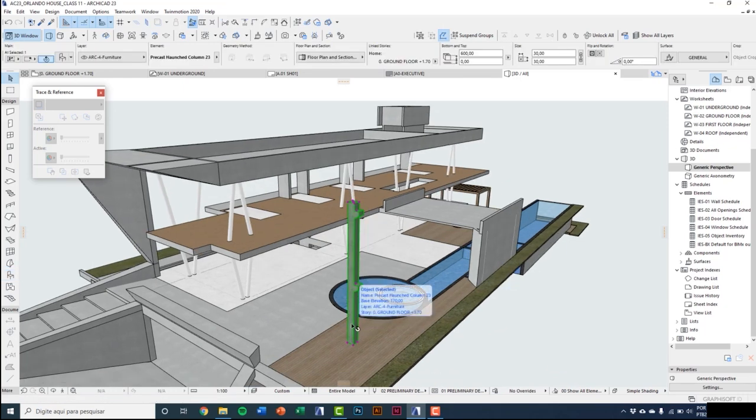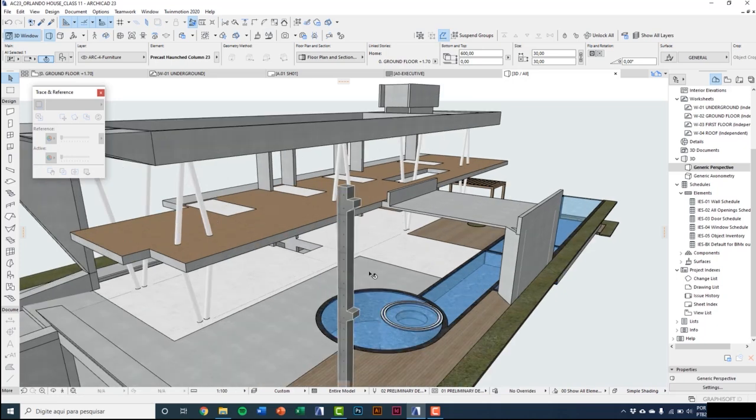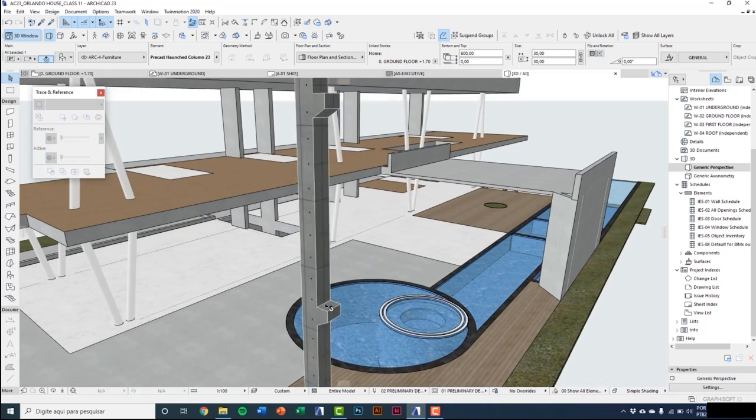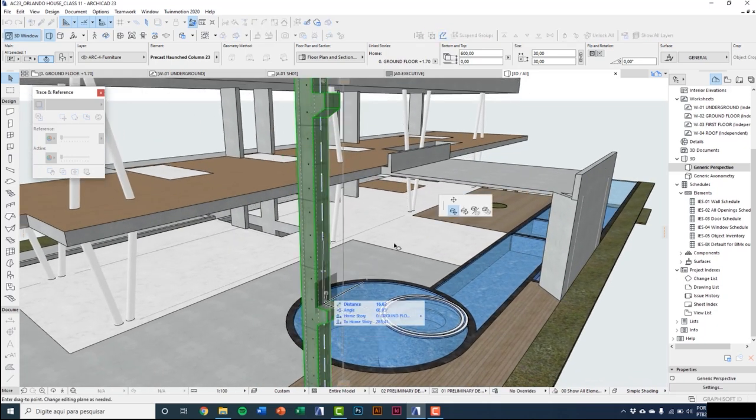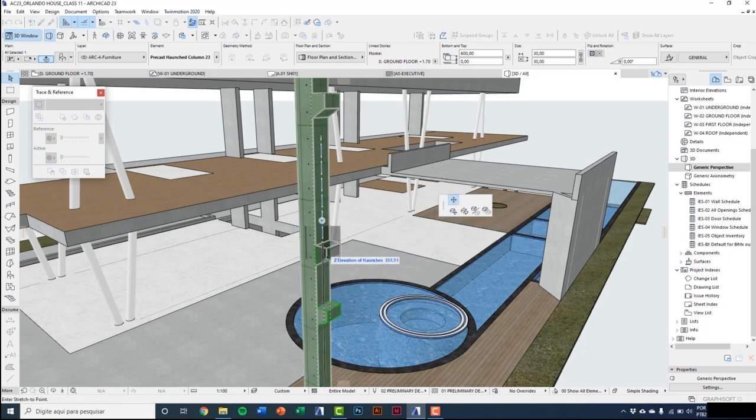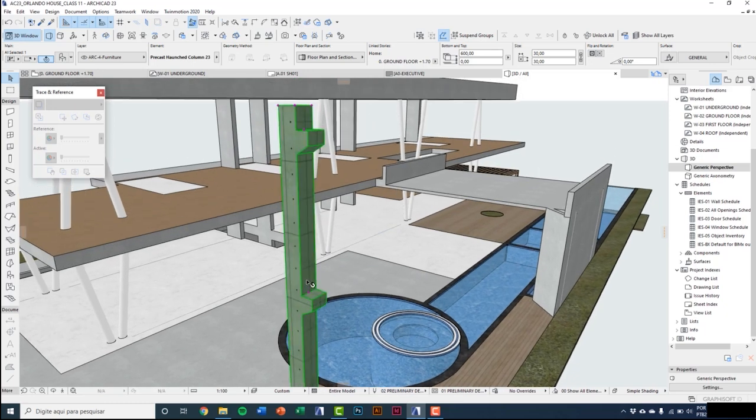Selecting it, you get adjusting even on 3D these support heights. Clicking on pink point. Here we have this option Move Node. So you can elevate as you want, or even type a specific value, in this object.